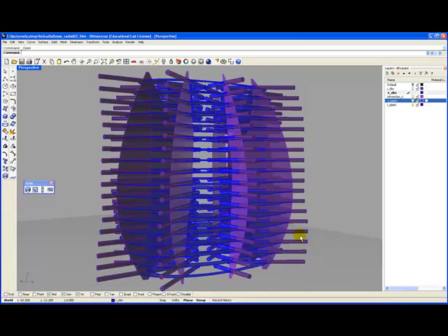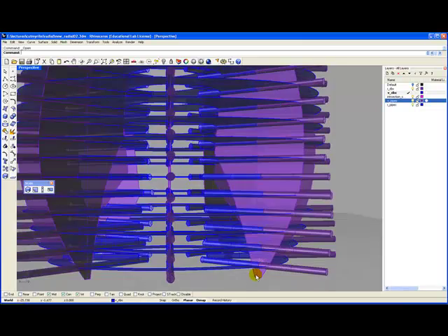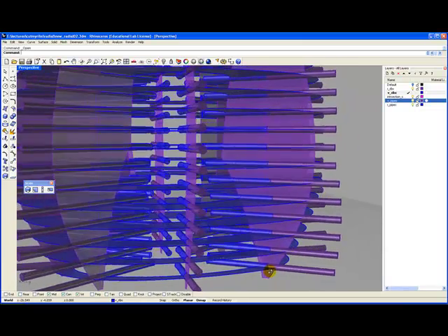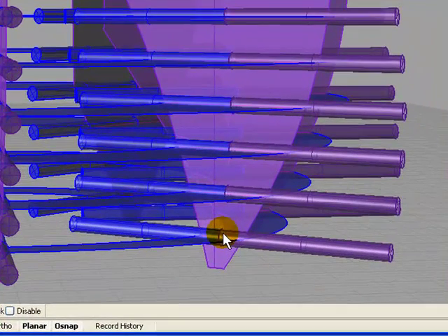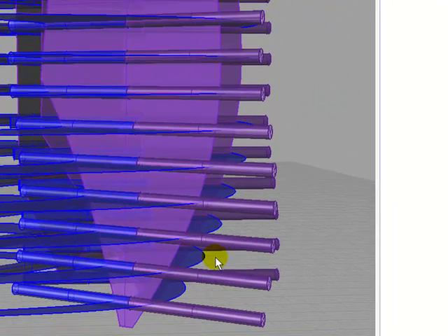This is one of the nice things about layer management. If I looked at this and were to run this the way that it's laid out here, my pipes wouldn't be cut in the way that I want them. I actually want the opposite. I want these notched in so that I can slide these in, and I want the vertical ribs sliced on the outside so that they notch that way. And that's a pretty straightforward fix.